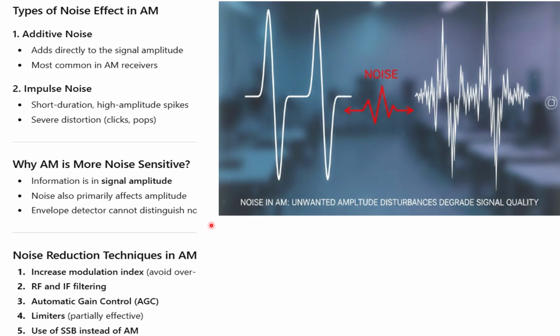The envelope detector will detect your message information from the envelope on the demodulation side, which detects the variation in amplitude only. Since you have already added some noise, the level of the modulated signal may go up and down because of the noise.